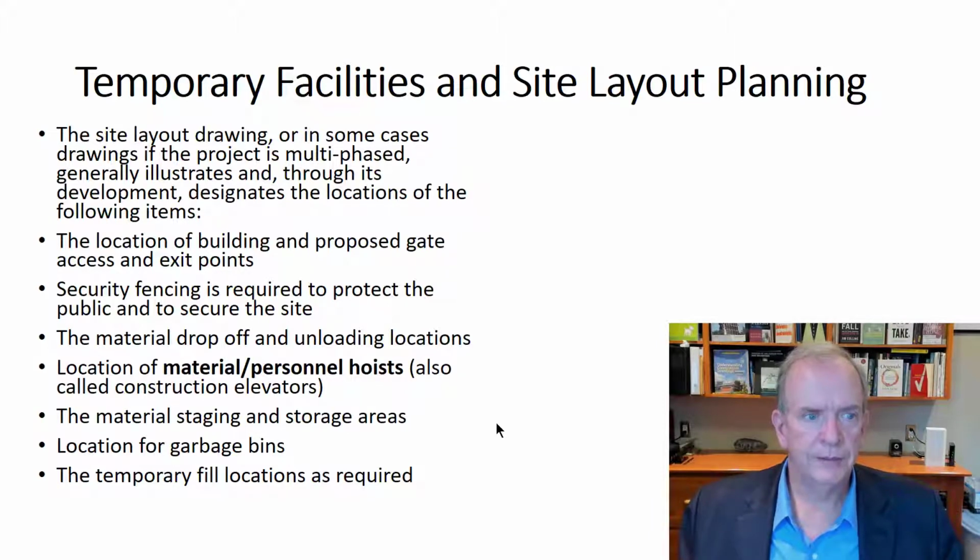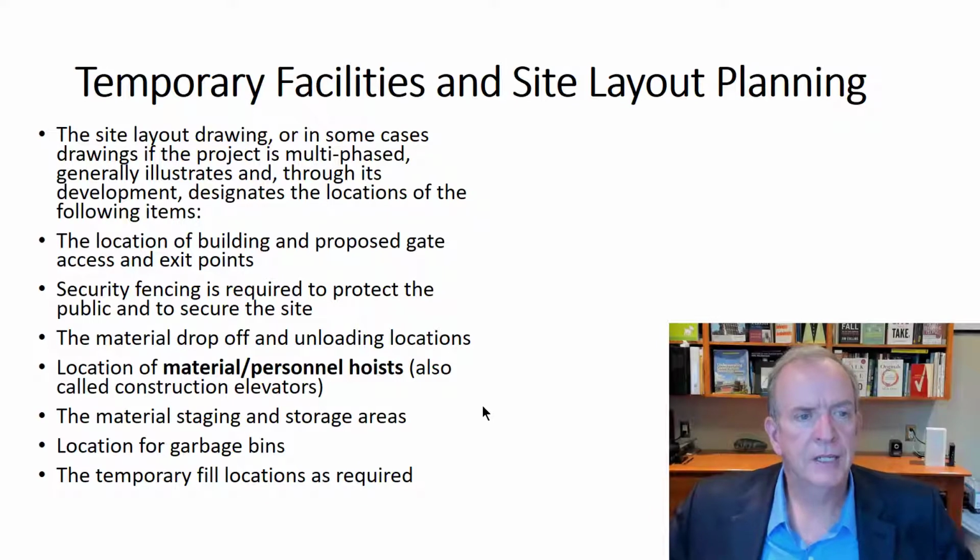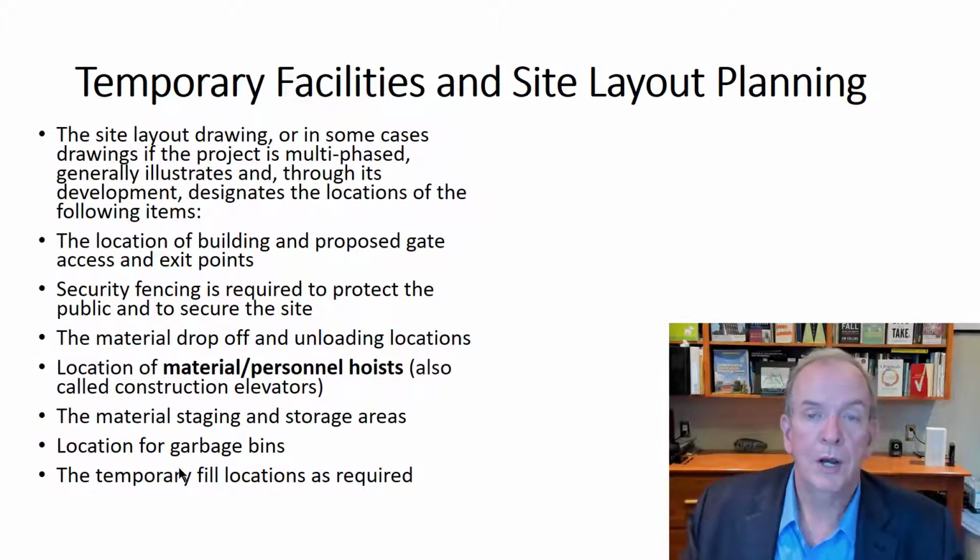Temporary facilities. So we have to think about all the temporary facilities, access points, how many gates are we going to have to enter the actual facility. You can do a job site layout drawing for the project, and I've got a couple of samples coming up, or at least one. Security fencing, material drop-off, unloading locations, the material hoist that we mentioned in the previous lecture, material staging, where are we going to put garbage bins?